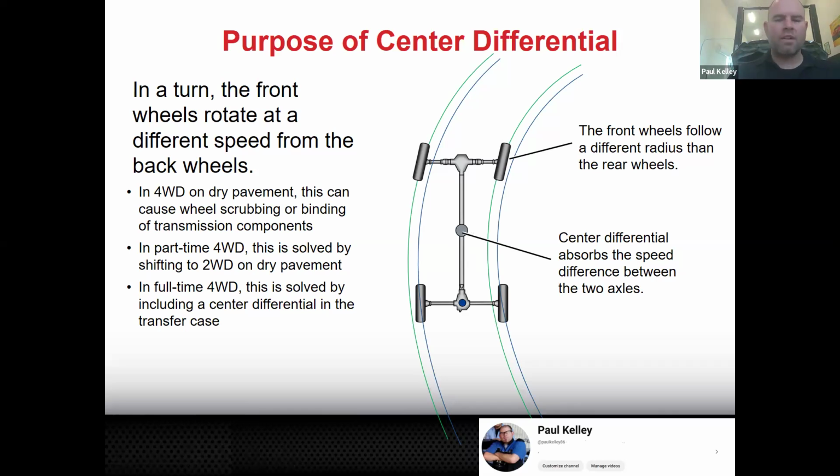Now, if it's an all-wheel drive, you need to log this info because we're going to cover differential types in a bit. If it's an all-wheel drive, that can mean a lot of different things. All-wheel drive is generally a marketing scheme. Sometimes the vehicles actually work more like a full-time four-wheel drive, but all-wheel drive as a marketing standpoint is for cars, whereas four-wheel drive is for trucks. If you get a smaller SUV and they don't want it to be like, oh, I got a 4x4, they'll call it an all-wheel drive, but the systems can vary drastically.